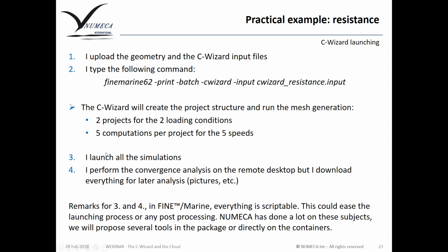When this is done, I will have to launch all the calculations myself, and I will need to perform, if I want, because I could stop there and retrieve all the data. I can perform the convergence analysis just to check that everything is okay, check the convergence for the drag, for the trim, for the sinkage, and so on. And when this is done and it's okay, I can download everything for later analysis.